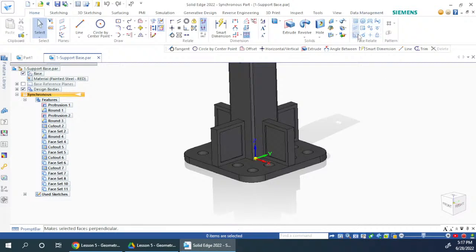And next thing that he was talking about is you can apply direct constraints on 3D models. Fine. So here we had seen some constraints were available for sketches. So all these constraints were applied on the sketches. But on this side, you can see it is called face relate. This is called just relate, which means they can be used only on sketches. But if you use face relate, they can be applied on different faces. So this works just like a feature.